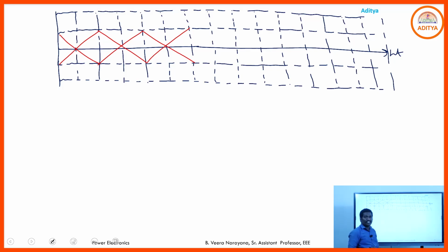If we go through the three-phase half wave converter, at a time a single SCR will be in the on state, so the phase voltage is transmitted to the load. So we concentrate on phase voltages, no problem. But in the three-phase full wave converters, the line voltages must be available across the load. So we concentrate on line voltages. So how do you draw the line voltages? You clearly indicate which is VAB, which is VAC, VBC, VBA, VCA and VCB. To draw those line voltages, you follow a simple procedure.